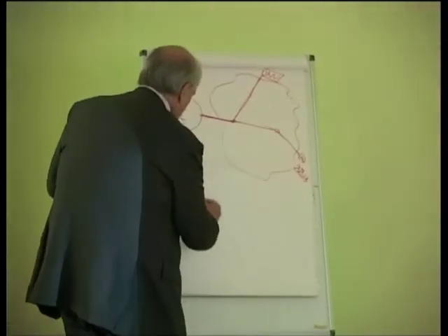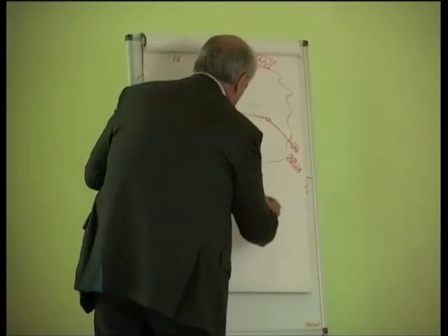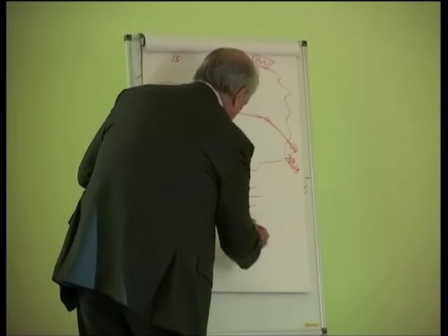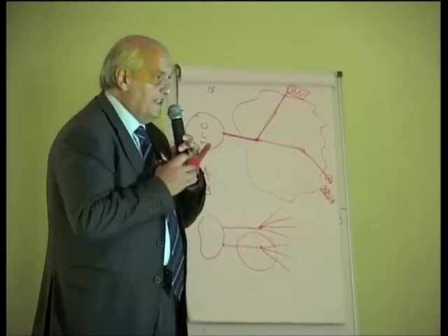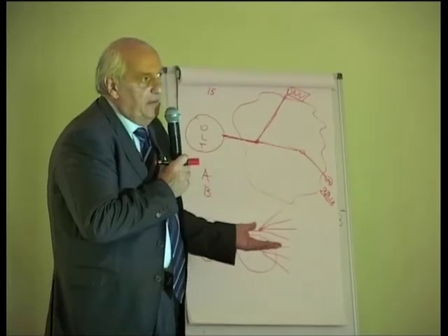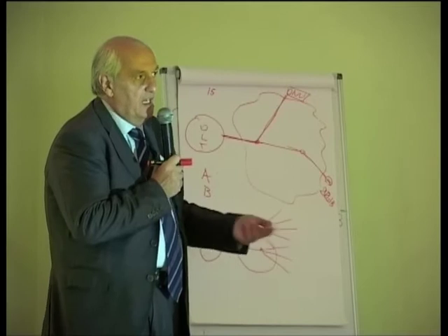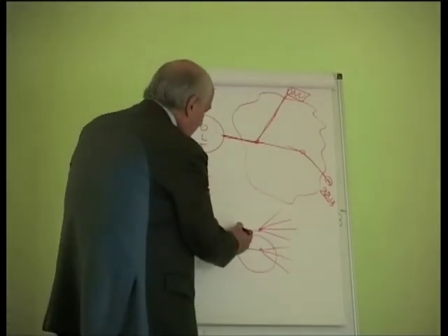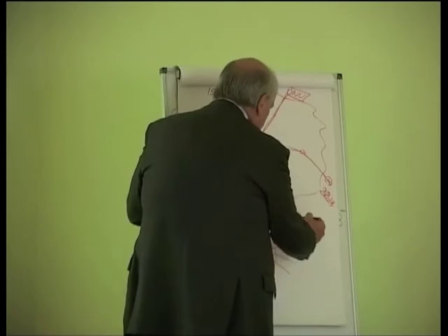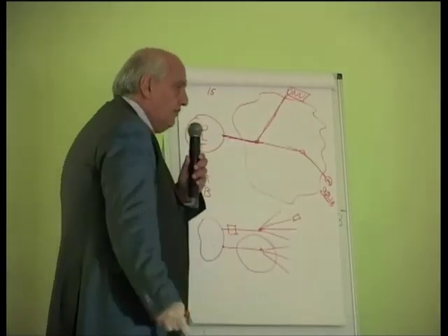To double all the installation. If you are going to use two fibers, you will pay twice the fiber plant. Of course, the excavation costs, the laying cost will be the same, because if you put one fiber or you put two fibers, you will spend the same money. But the fiber is costlier than having a WDM coupler here and here. Normally, the fiber has a much higher cost than the WDM couplers. The WDM couplers can be bought for a few tens of dollars.